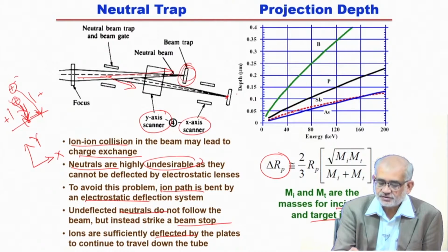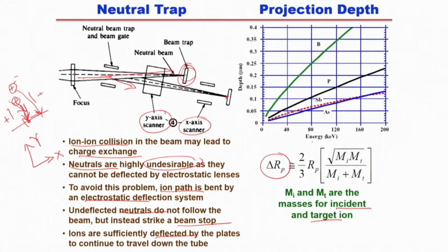Now, we already saw, and this is again very clearly shown, that whether it's arsenic or antimony or phosphorus or bismuth, whatever species you want to implant, in all the cases the depth to which they penetrate is directly related to the energy. So as you increase the excitation energy from say 30-40 keV to 160-200 keV, the depth that you penetrate to will be greater, and that allows us to control the depth of penetration precisely up to the extent we want.